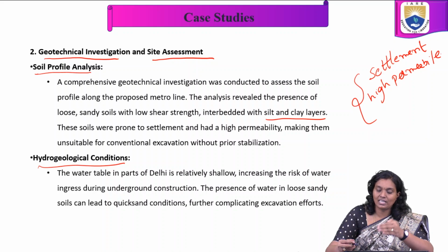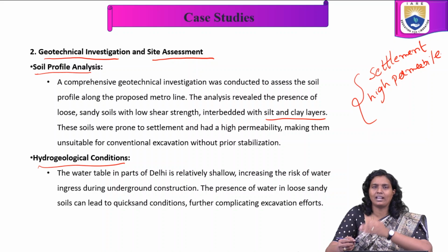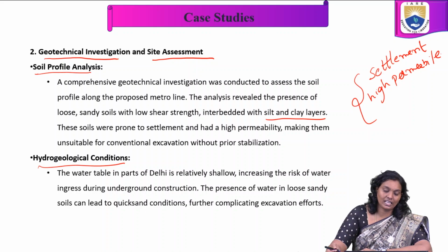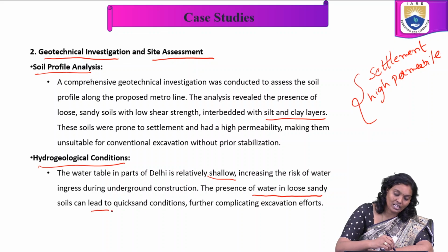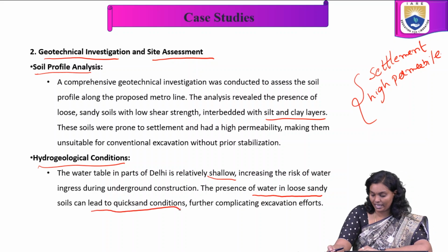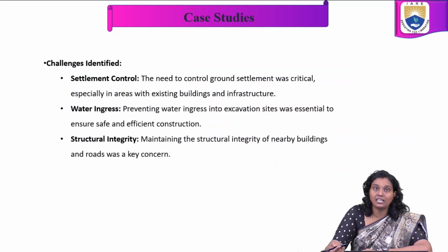So once we understand the type of the soil, what kind of challenges are we going to understand? In hydrogeological condition, the water table in parts of Delhi is relatively shallow, increasing the risk of water ingress during the construction. The presence of water in loose sandy soils can lead to quicksand conditions, further complicating the excavation efforts. So these are the challenges we identified.